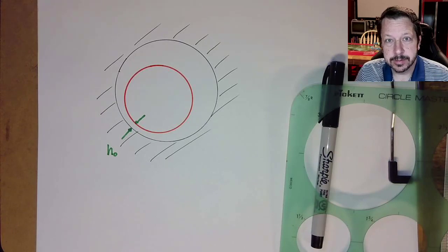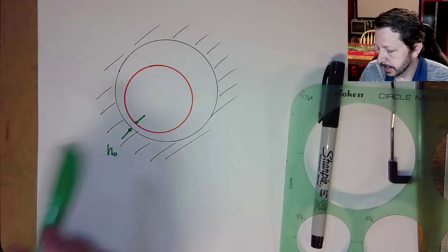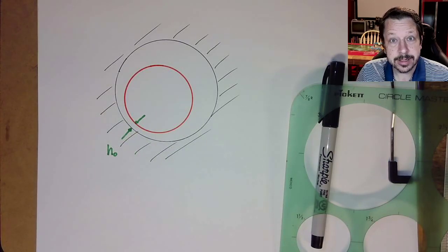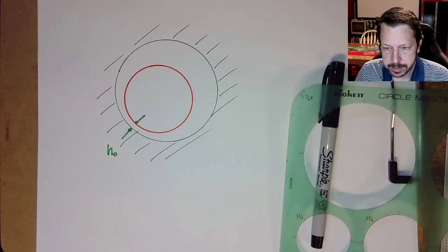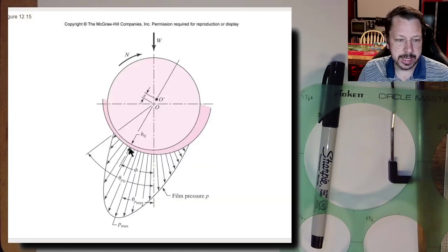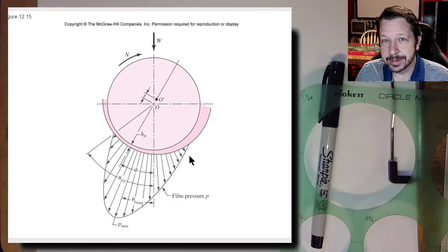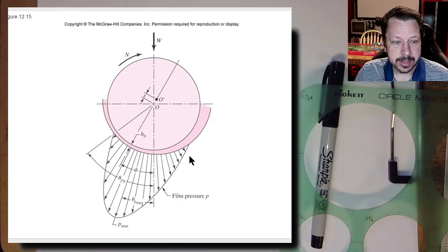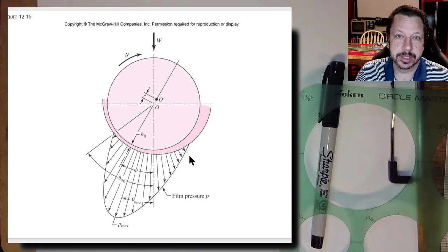So it's talking about the lubricant being the film, and that's the location where it is thinnest. So minimum film thickness. On this other diagram, you can kind of see a pressure distribution. Remember what we did when we calculated pressure last time was we just used a projected area, kind of like you would with a bearing stress in between a bolt and a hole that the bolt is in. But this is more realistic pressure distribution.